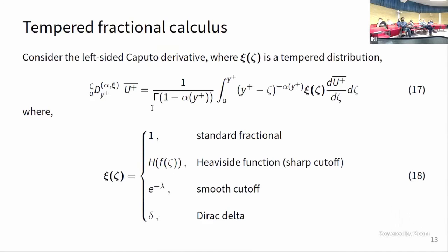His model cannot go back to local, but I think if there is such a construction, I can introduce a Dirac function, and probably I can make the non-local model go local as well, because apparently there is a duality near the wall region. When the fractional order is unity, it makes perfect sense to have a local operator, and beyond that viscous sublayer, you need a non-local operator. So this duality becomes very difficult to address. I was lucky because the fractional operator naturally, by definition, addresses all those things.